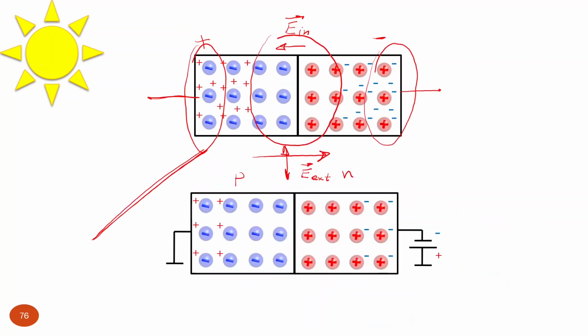So under open circuit condition, which is steady state, we don't change the amount of photons per second which illuminate our solar cell, then we get a steady state concentration of non-equilibrium minority charge carriers, and steady state forward bias because of illumination.